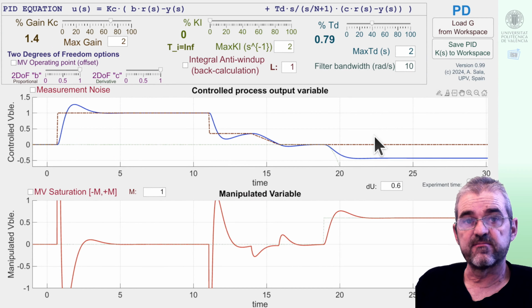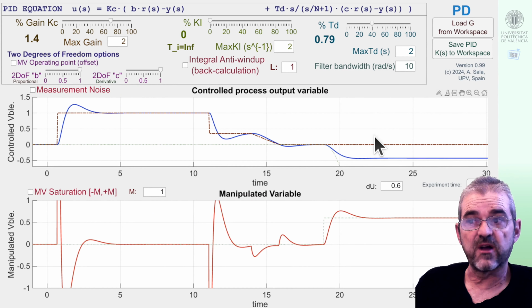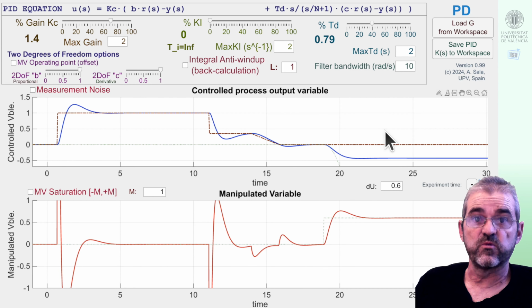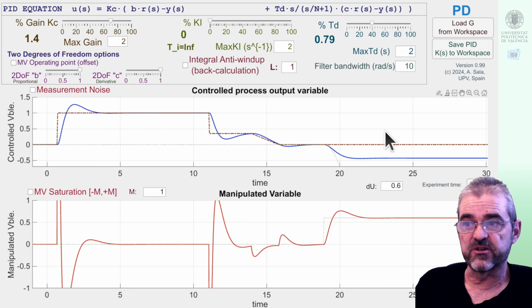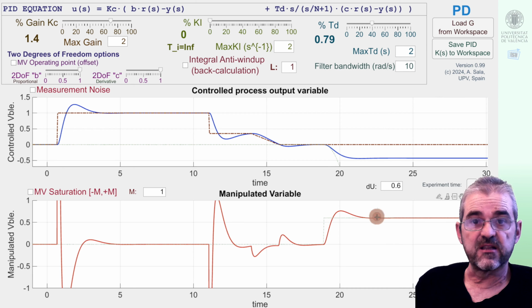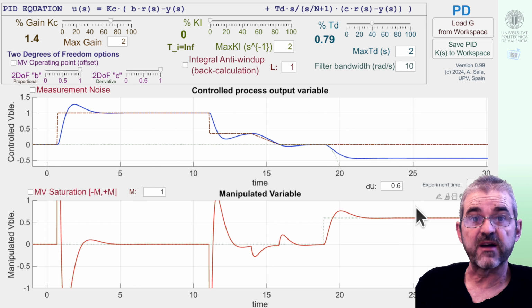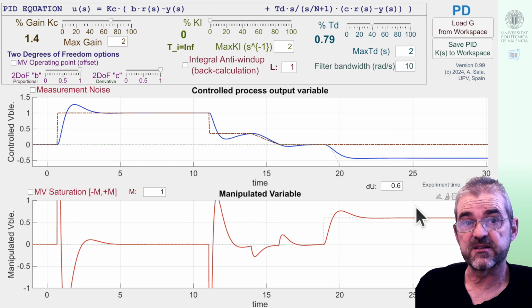This is my requirement. And in this case, for instance, how large was the disturbance amplitude? Well, it was 0.6, not because we directly measured it, but we have an indirect measurement. If we have a controller in operation and my controller ended up making 0.6 newtons of force in order to stop the mass moving, then if the mass stopped moving, it means that the resulting force is 0.